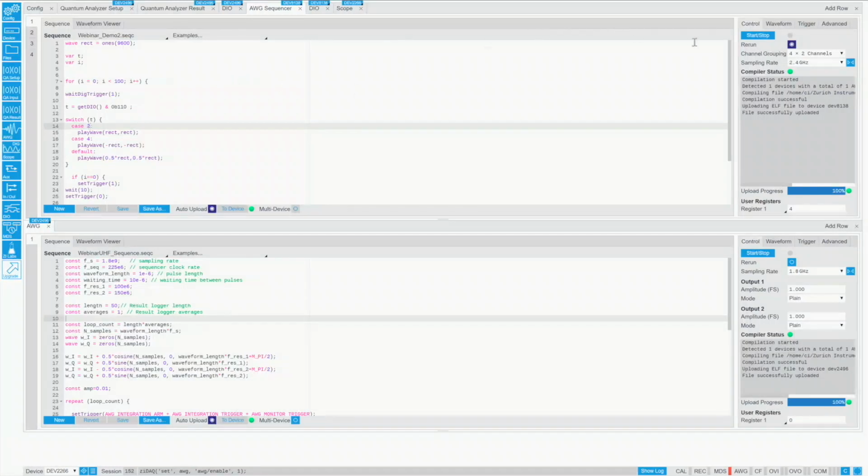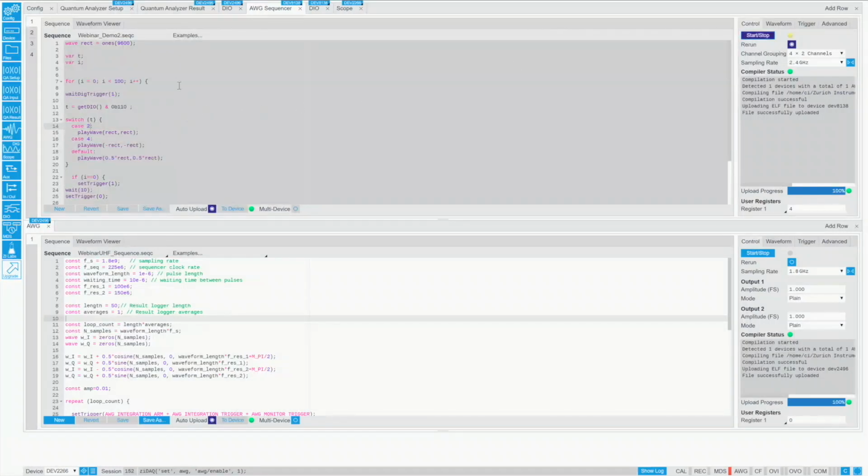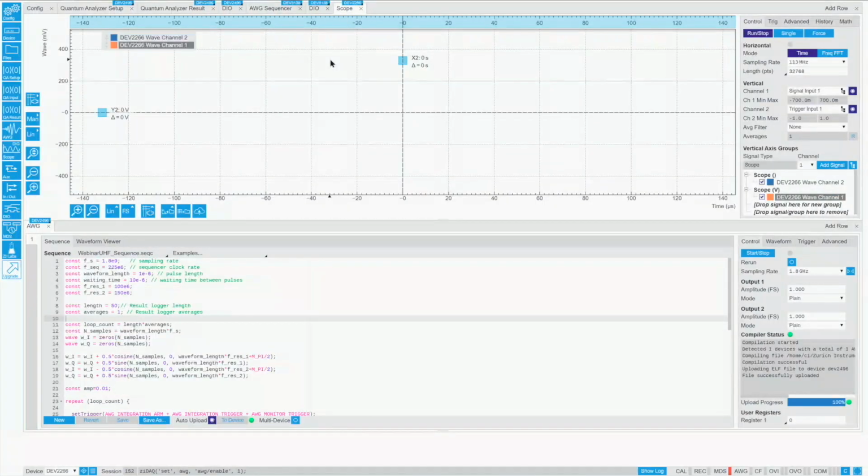Good. So now let's start the sequencer and have it wait for the results. And now we look again at our scope. This is again the other UHFQA, just as a reminder, but essentially you can just see it as a scope, and we will look at the signal input and the trigger input. Now we just start our simulated measurement, and if we do this, you indeed see an alternating sequence of pulses roughly every 25 microseconds, which is currently the time that we wait until the next readout is simulated.